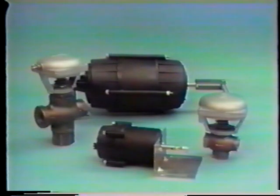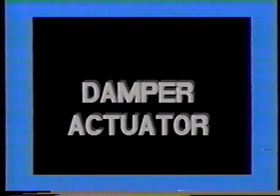Air pressure is converted to a force by utilizing a signal pressure to operate an actuator controlling a valve or damper. The valve body or damper provides the means to regulate the controlled medium. We will discuss the various damper actuators and valve body configurations in this section of the presentation. First, let's take a look at the construction of a damper actuator.